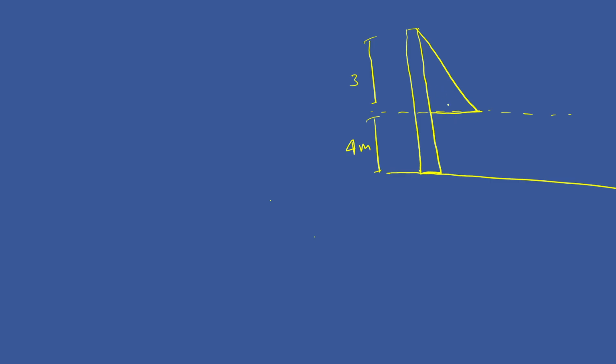So this particular value will be k into gamma into h, and here it will be h1. Then we have another stress block which will be acting on this particular part, but due to the soil medium available above.